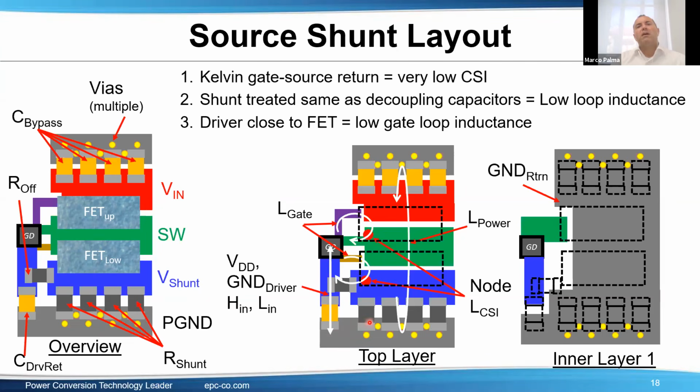And you also have to take care of driving carefully the signal Kelvin points, which are then covered by the ground reference for amplifying the signal of the shunt resistor, so that you get away from the switching node and then you can amplify somewhere else the drop of the shunt resistor.